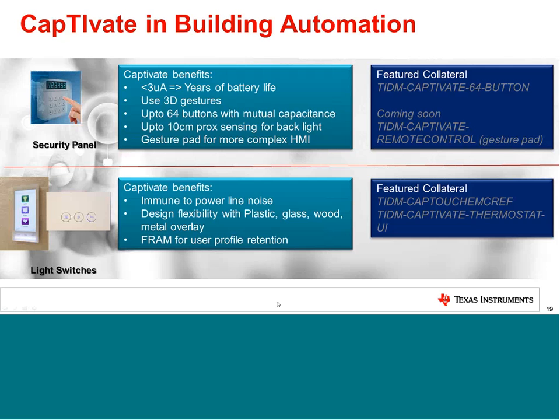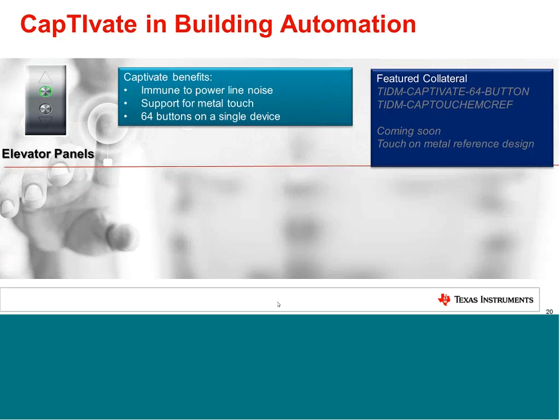Again, power line noise immunity becomes important there. As I said, we have IEC 61000-4 certification. And if you look at the TI design, the TIDM CapTouch EMC test, that will tell you exactly how you can design a system that will work for an EMC situation.